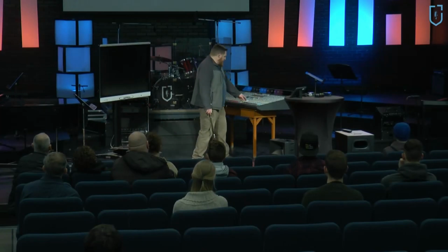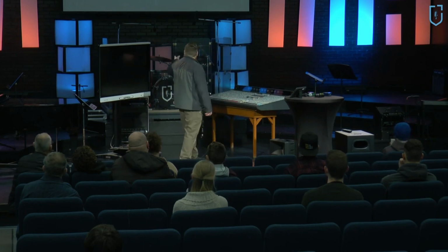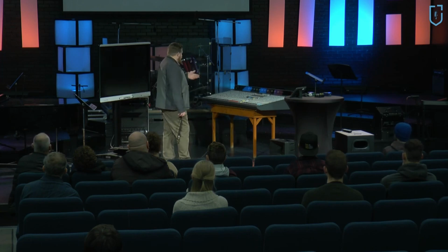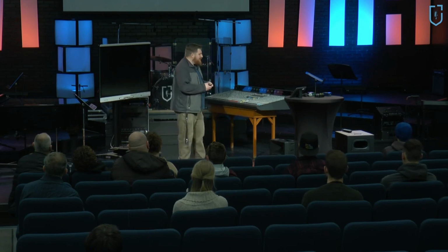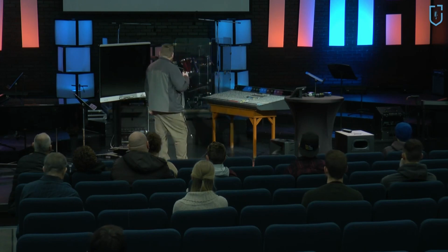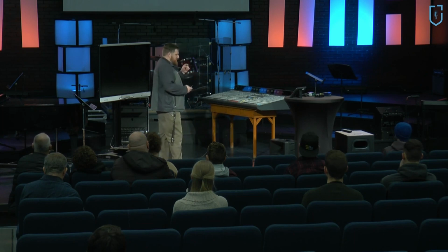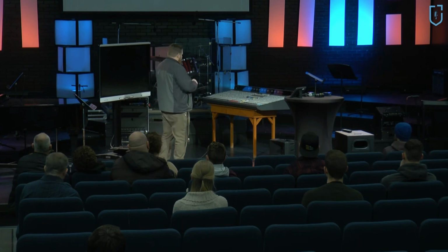This board here has 4 stereo inputs. So it's one fader, but it's designed to take in 2 channels at once. And that'll give you your left, right. And then it'll either be RCA, that's that red and white plug from VCRs, if you guys remember those things. You can go with 1/4 inch TS, so one would be your left, one would be your right. And then the stereo channels are often numbered as like 21, 22.